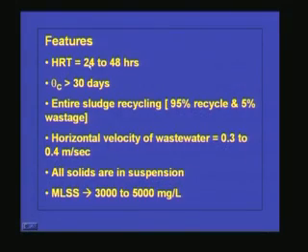And the features of this oxidation ditch: the HRT varies from 24 to 48 hours, and theta C, the biological sludge retention time, is more than 30 days, and entire sludge is recycling. Usually what happens, around 95% of the sludge is recycled and 5% is wastage.